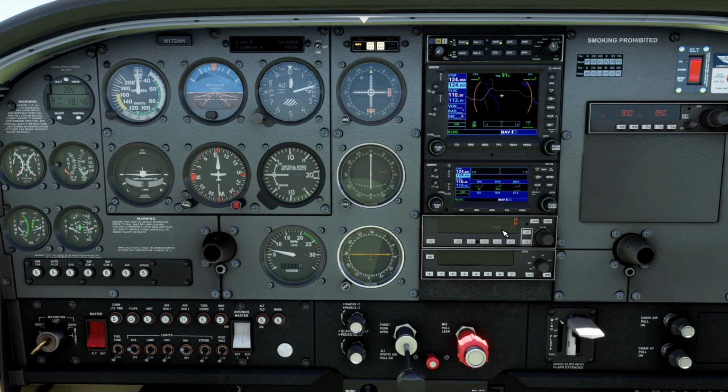And honestly, I don't know that it would be on if we were higher than 1,000 feet, because it only comes on within 800 feet of whatever's in the pre-select window. So I have to try that out at a higher field sometime. One little note about the power-up is that if you drop into Flight Simulator in flight, if you start your session flying in the air, it will go through this self-test, and then it will automatically engage the autopilot, and it will engage it in the wing leveler roll mode, but no vertical mode. So the autopilot will automatically engage, and you'll either have to disconnect it or set it up for what you want to do.